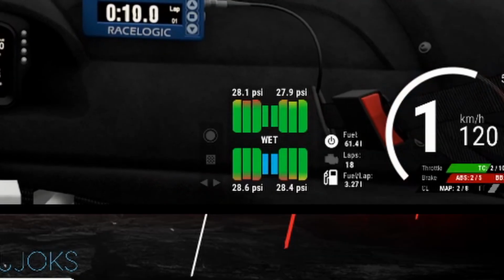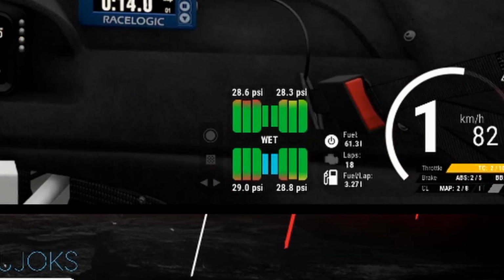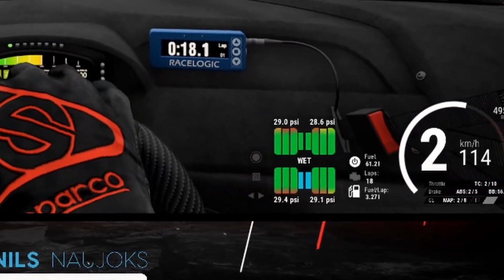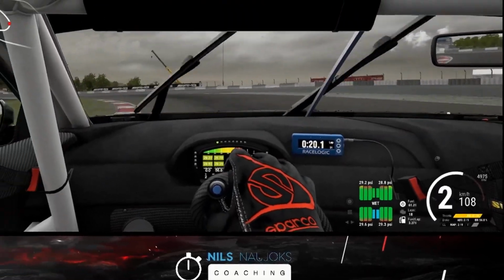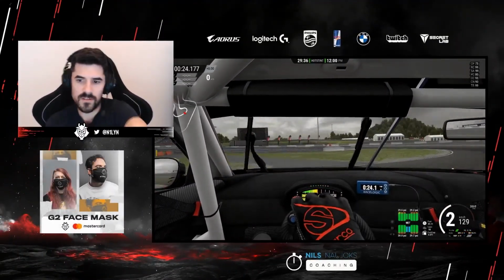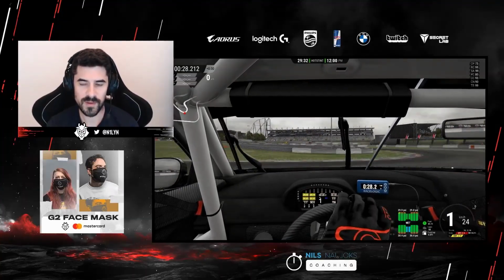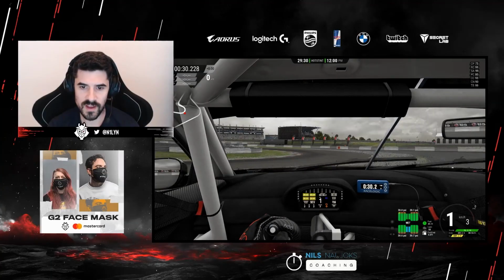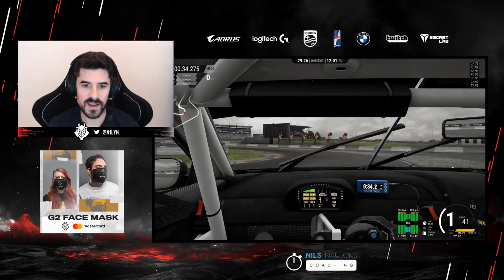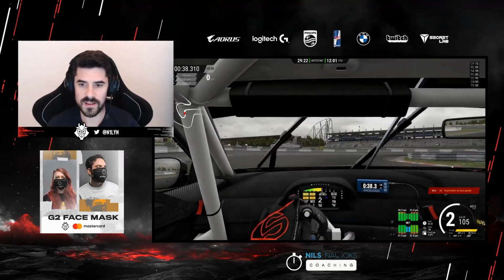The surface goes red right away in the first corner. You can see the pressures are increasing massively and very quickly right now. Even though it's still kind of driving, it's very certain that you'll be using this tire a lot. You can also see it's very slippery on occasions, especially when the surface temperature is so high already. So let's say part of that was a driving error, and the other part was certainly the tire not being anywhere near where it needs to be.